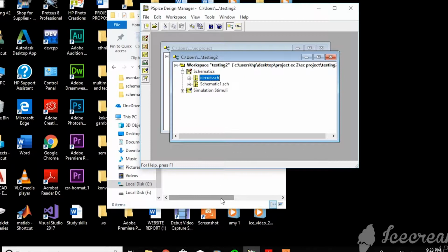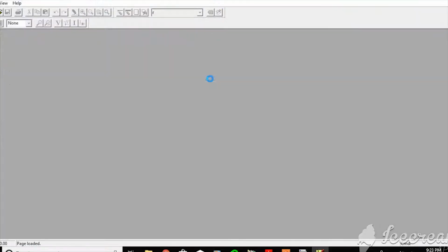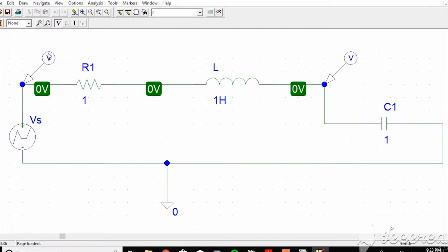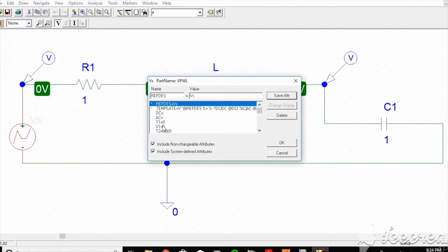For a different staircase function, the steps for the second staircase are the same as staircase 1, but we change the VS input to V1 0, V2 6, V3 6, V4 30, V5 30, V6 negative 3, V7 negative 3 and V8 0, and Save and OK.